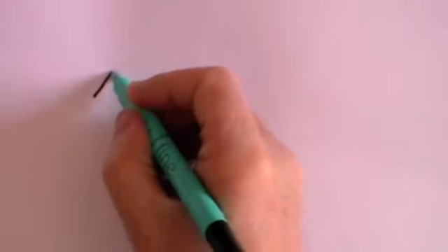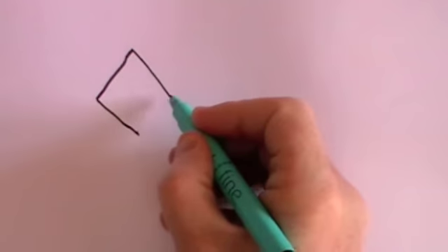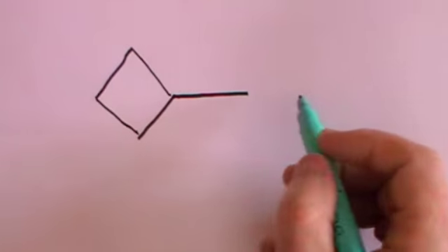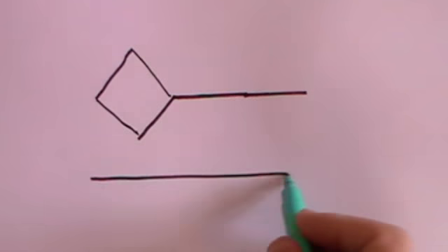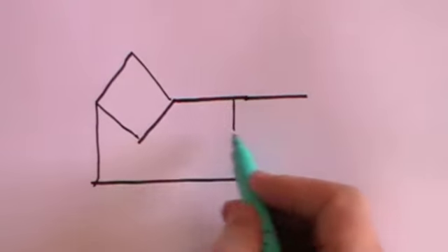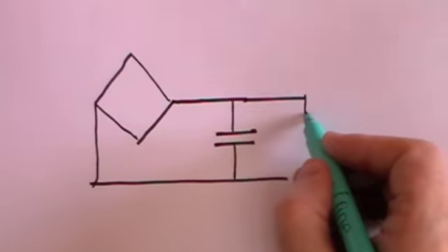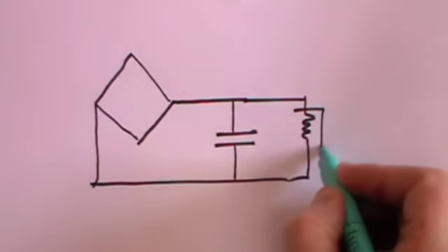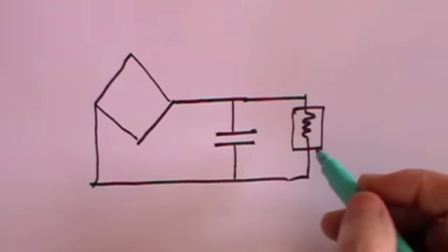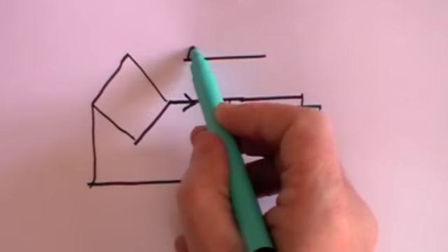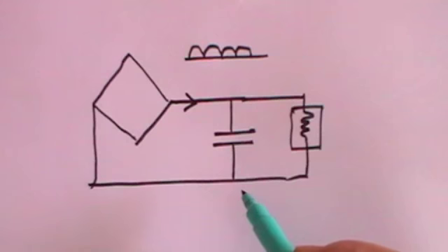What's the solution? Well, what we do is we take the output of our bridge rectifier. I won't bother drawing in the diodes. It's exactly the same diagram as before, but here is the output. And what you will need to do is to put a capacitor, a large capacitor, in here, and now this can be your computer, which is your appliance. What happens? We know that the current is only going to flow in this direction, but it's going to be a constantly changing current and voltage.